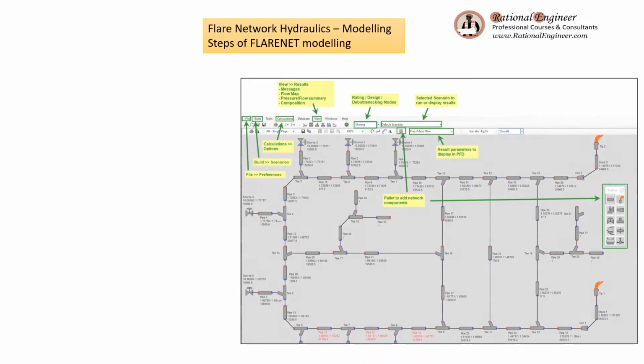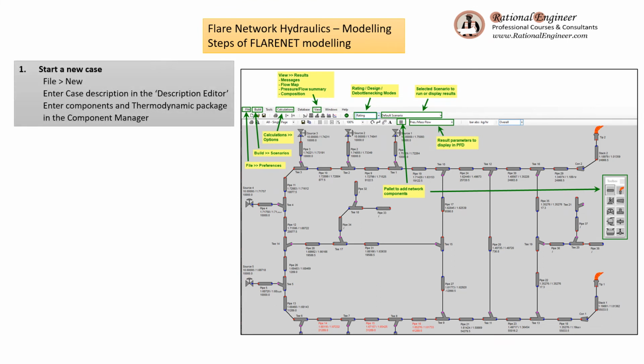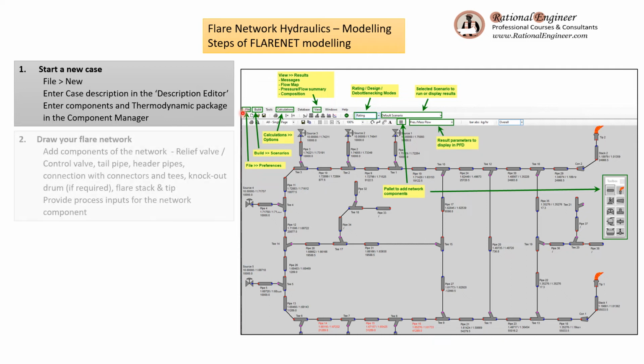Let's look at the high-level steps to set up and run the Flarenet model. Step 1. Start a new case. Press the File, New, enter the case description, enter the number of components of your fluid, select the thermodynamic package. Next, you can draw your network.